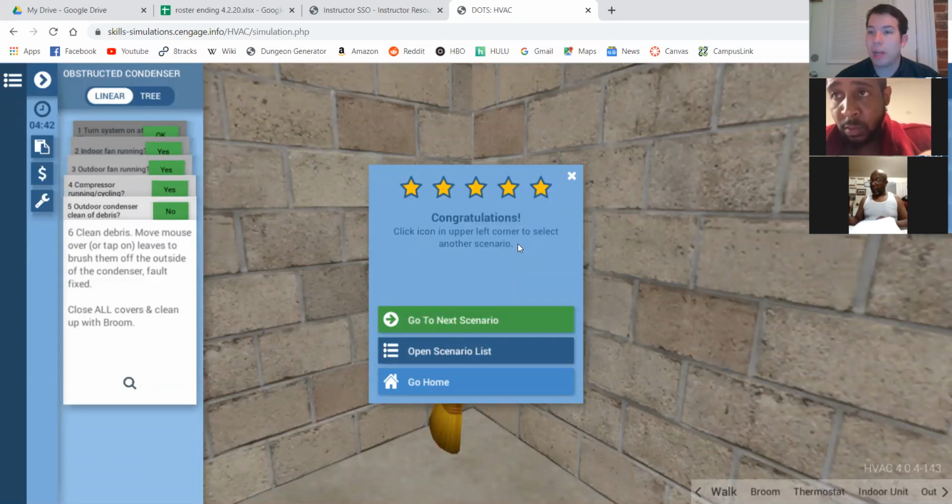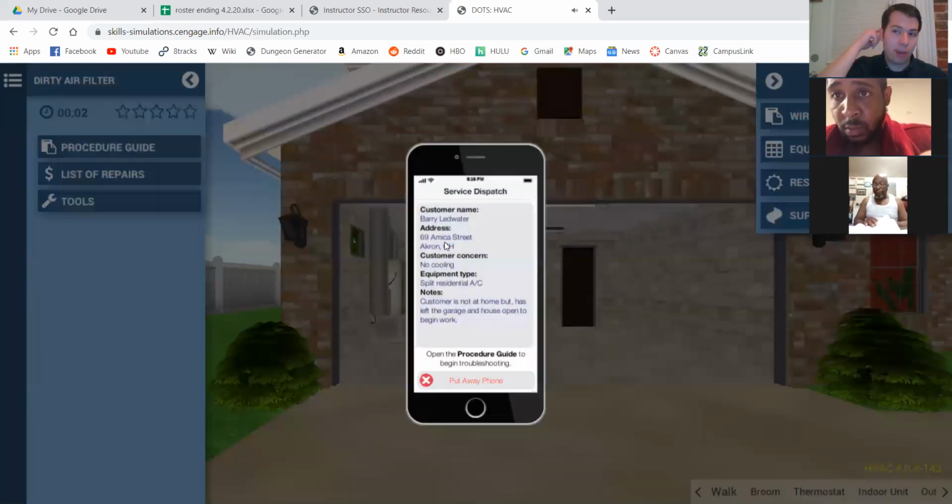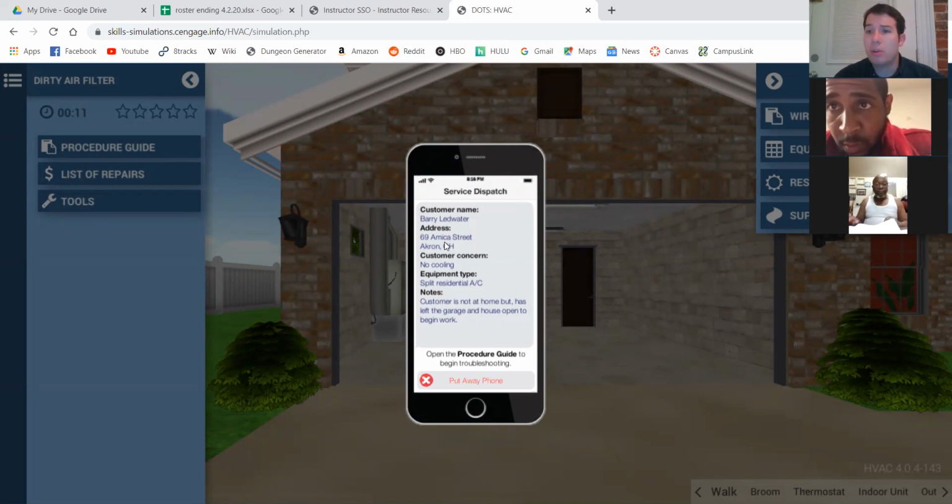And they're going to start paying more and more attention to that kind of stuff, because more of that debris building up on there is what's going to give us a difficulty with heat transfer. It basically acts as an insulator. So you can have that with the indoor unit, just by having a dirty air filter. For the outdoor unit, you're typically going to see the coil get debris over time. Look at the elements. Look at what it's surrounded by. Is it near some bushes? Is it near some trees that might have really high amounts of pollen?